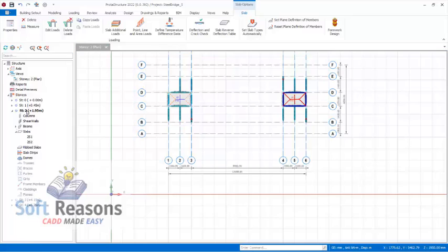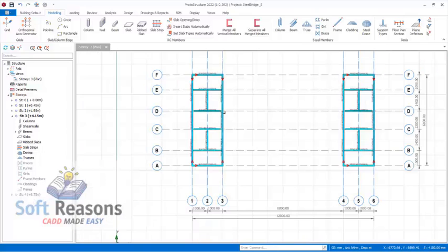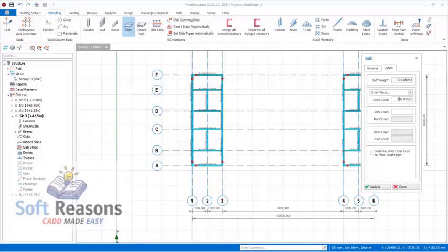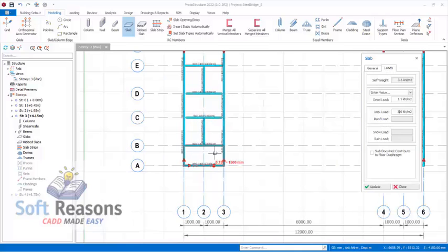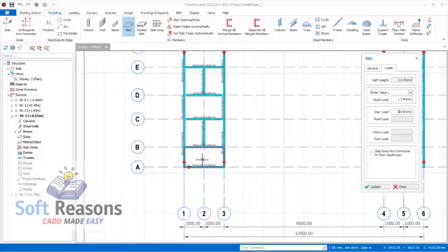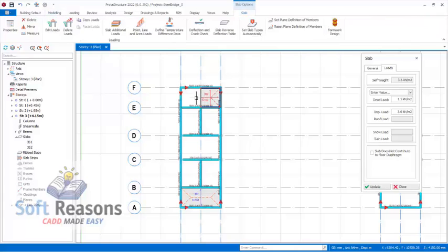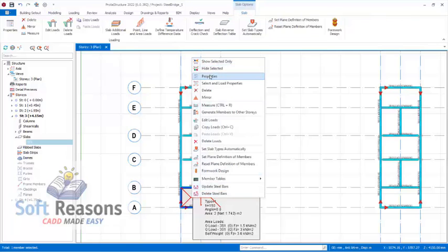So we navigate to the next level, which is going to be level 3. Double click on the level 3. At this level 3, we still navigate to the reinforced concrete slab, 150, 1.5, and then we use 3 kilonewton per square meter, because here we have a slab here. Sorry, this is supposed to be a cross, not only a dot provision, so we can get rid of that by deleting it. So we use this property.